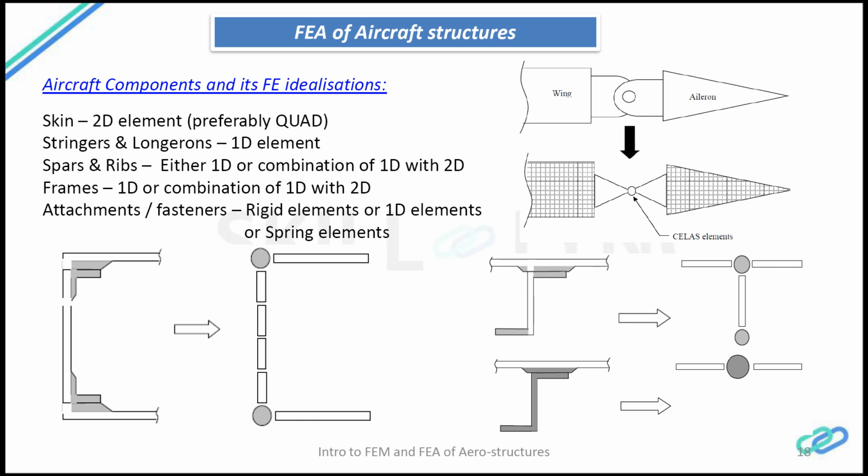So the user has to specify the shear stiffness and axial stiffness of the bolt. He has to calculate them based on the bolt geometry and fastener spec, calculate the axial stiffness and the shear stiffness, and then feed those values into the tool.